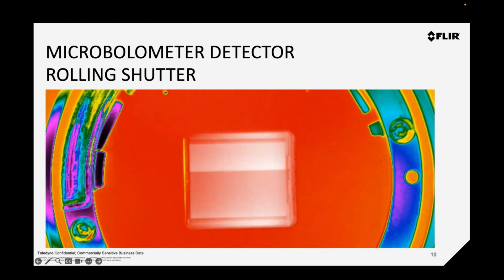Thermal time constants are clearly the challenge for microbolometers when it comes to going faster. So you might ask the question, why hasn't this been addressed? Well, the response of the detector is directly related to thermal resistance. And any efforts to decrease that resistance, you could thin the detector element, you could decrease the size, will actually have a directly proportional effect on the sensitivity, which would bring it to an unacceptable level. So, needless to say, this is not trivial, and it's a challenge for the entire industry, and this is where bolometers are actually at today.